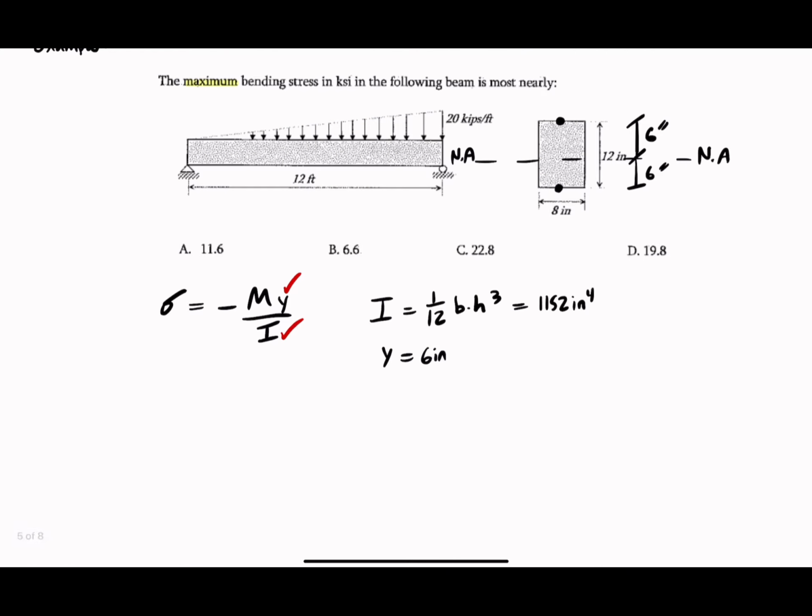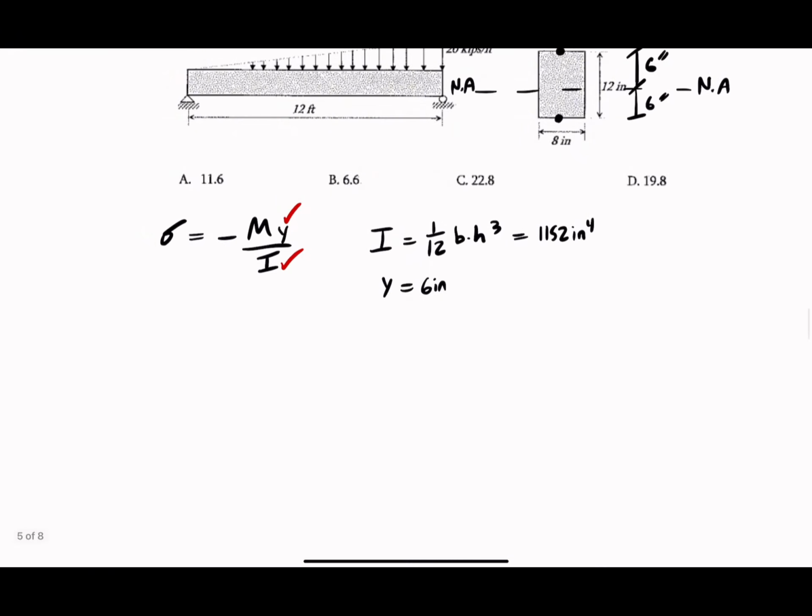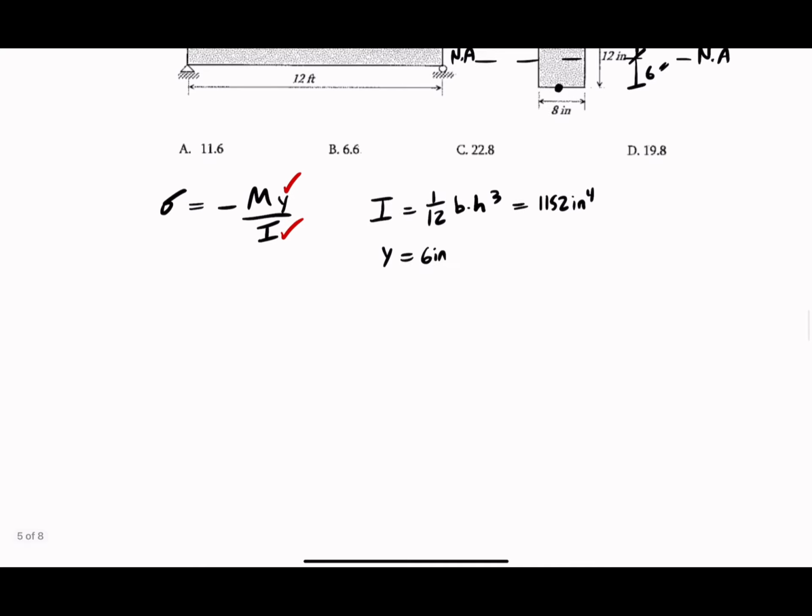Finding the point at which the shear will be 0, and then taking the area under the curve is going to be difficult if we do the bending moment and shear diagrams, and we may end up having to integrate anyways. So I think the best route is probably to just go ahead and integrate this from the start. So I'll show you how to do that. So I'll redraw our beam here.